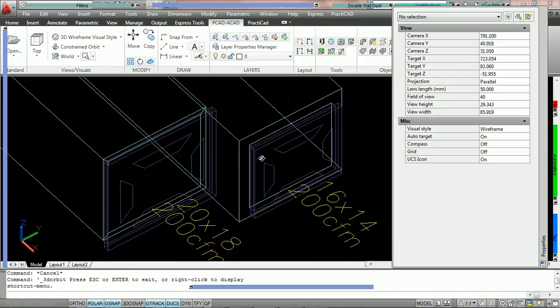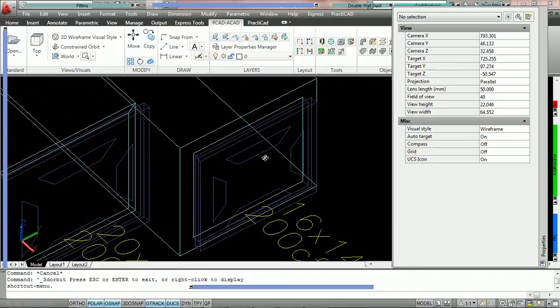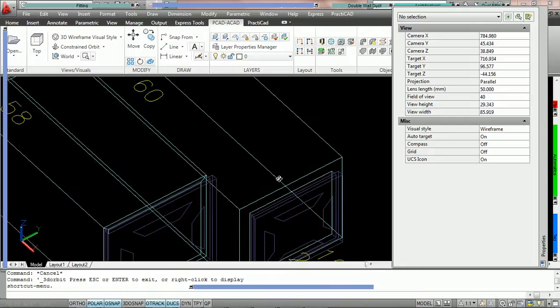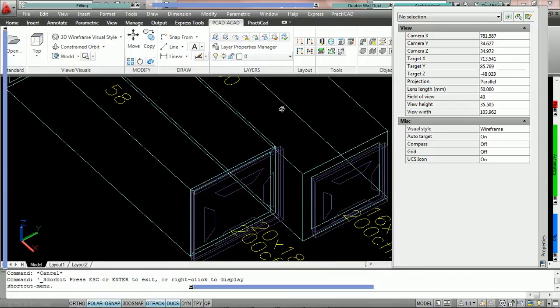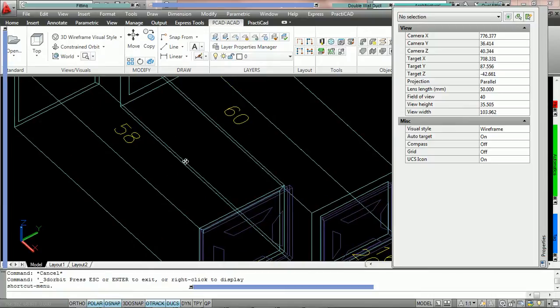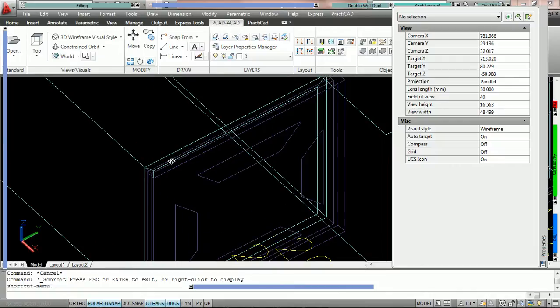However, with the connector flange parameter, when you snap a grill, it snaps the neck to the inside of the connector flange. Now this flange, regardless of how large or small you make the value, has no bearing on the length of the fitting. So you can see that this fitting here is 60 inches, the one with the PCAD connector on it. The one we did the 1-inch flange in, we made the connector size 1 inch. So we lost an inch on each side of the fitting to create this connector.